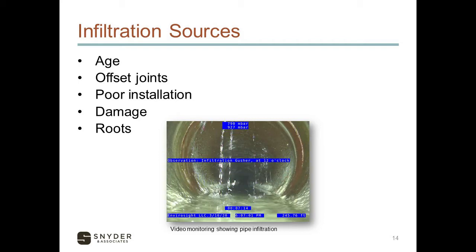We see a lot of plastics. If you get a poor installation with a clay pipe, you're going to see a lot of cracking and a lot more susceptibility to seeing those defects that are going to allow clear water to enter the pipe below the surface and cause that damage.